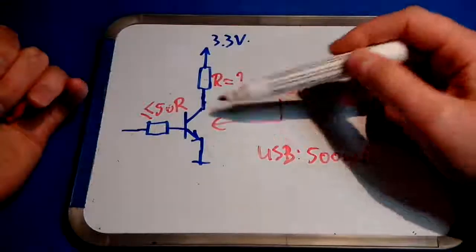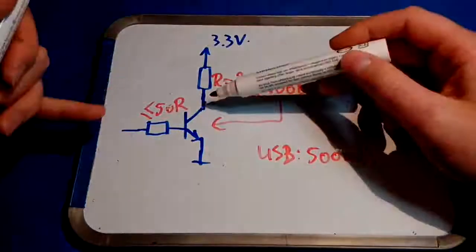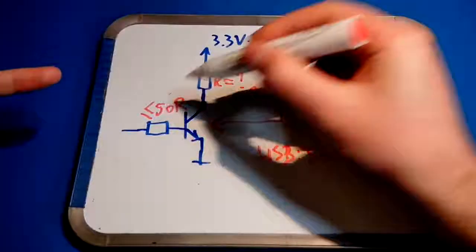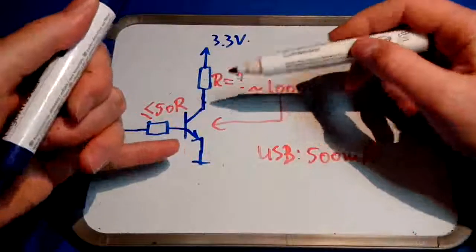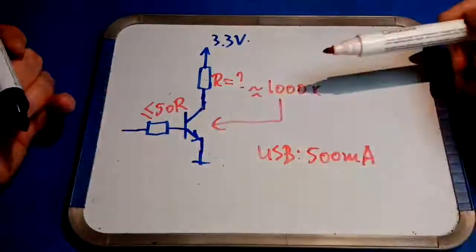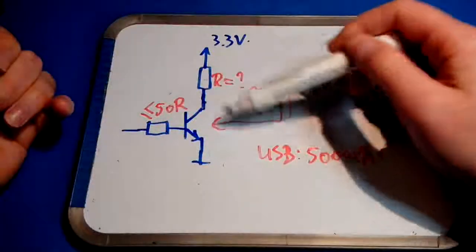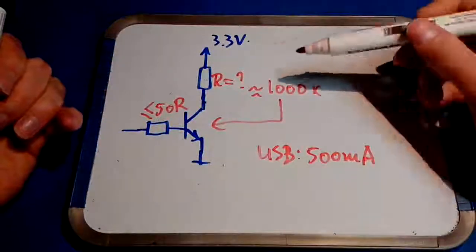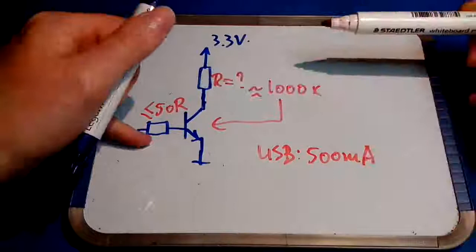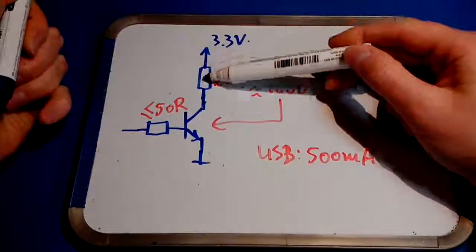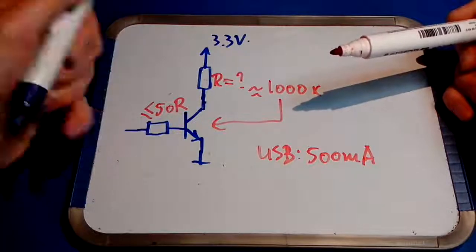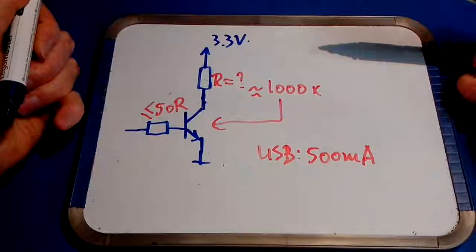Now let's say we have 1000 of these transistors in the CPU. This, as we saw, is an inverter. There are some other logic gates that look exactly like this. There's always a pull-up resistor, there's always a transistor, one or two below the pull-up resistor, so it all looks pretty much the same. So worst case, as you can see, this topmost resistor is much smaller than this leftmost resistor, so the current through the topmost resistor will be dominant. The current through the leftmost resistor will be much smaller, so we can ignore that for now. So let's focus on the topmost resistor.